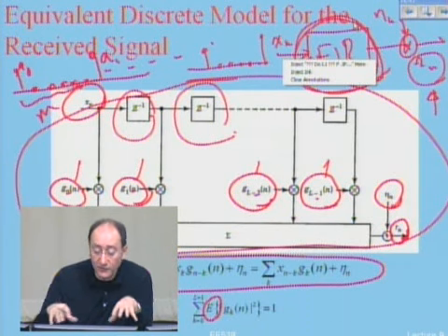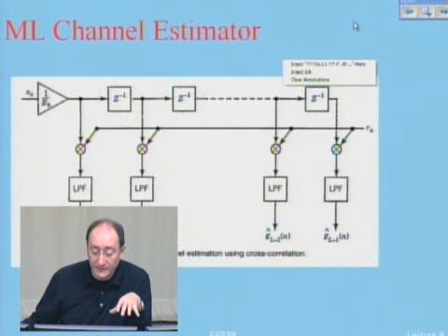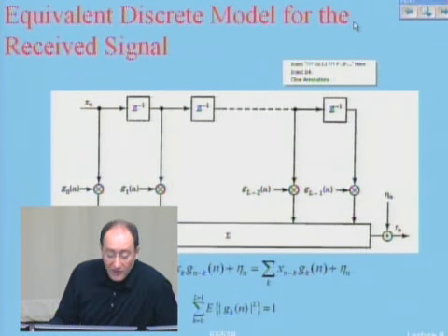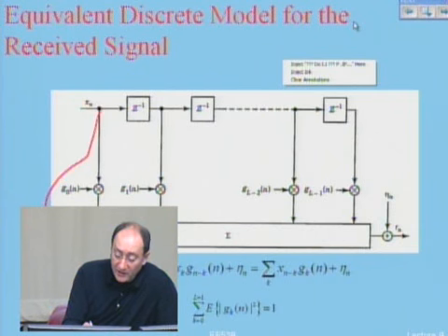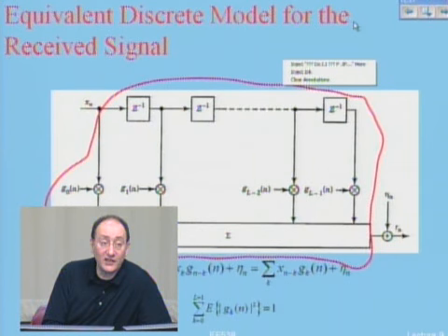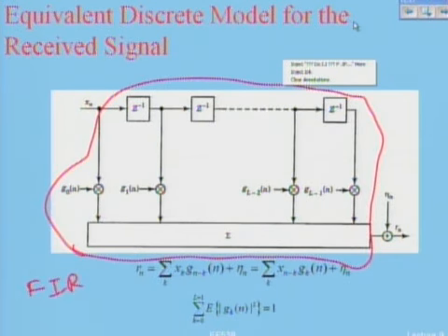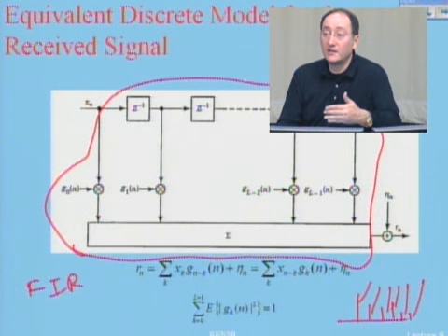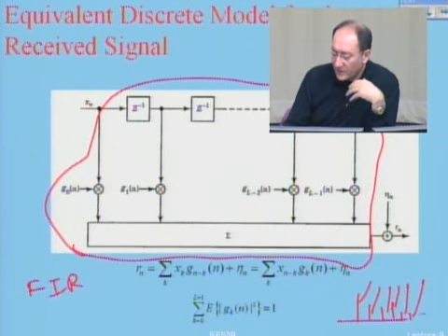So basically what I have told you so far was that if I want to model the channel, it is modeled by what? By a tap delay line. Tap delay line is the old name for FIR filters. An FIR filter with what? With an impulse response like this, for example, in which each of these taps is changing according to fading. Have you seen something similar to that?